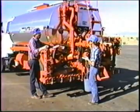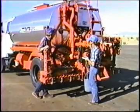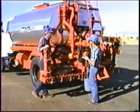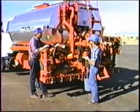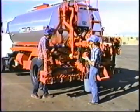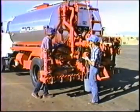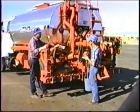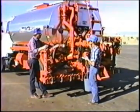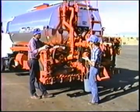That is, it calculates and adjusts the asphalt pump to that. Again, it's got to have all its information. It has to have travel speed from the rear end. It has to have bar width from the control panel. It has to have desired spread rate from what we've put into it, and finally it's got to have gallon per minute information. If it has all that information, then the computer exactly regulates the asphalt pump to the required gallons per minute.